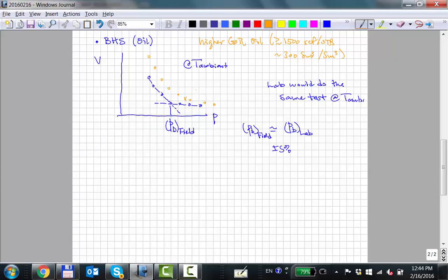Let's say the bubble point was there, but what you would see is that it's kind of curving above the bubble point and below the bubble point, and that's because even as a single phase liquid above the bubble point, it's quite compressible. So the volume is expanding, not linearly like this, but it's kind of curved the whole way.